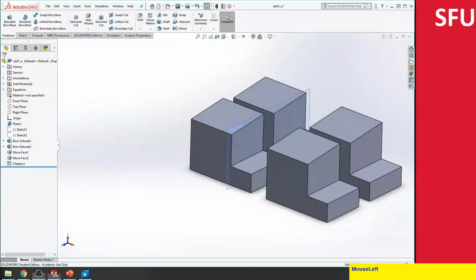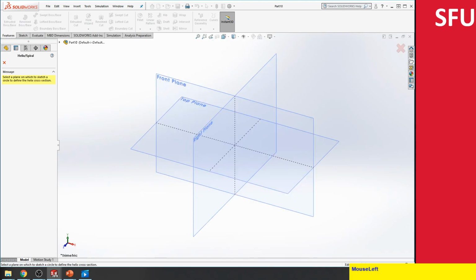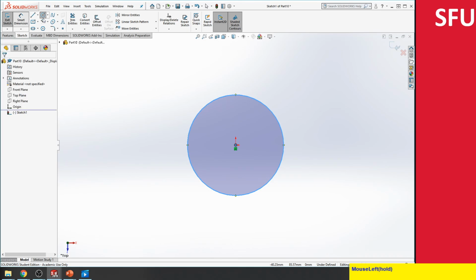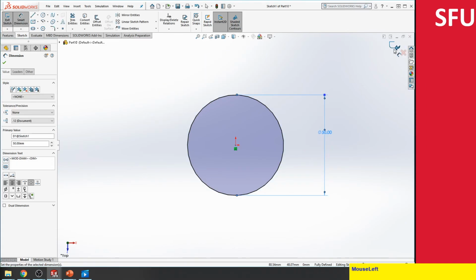So let's see. So here is my SolidWorks. So let's do a new drawing. So I'm going to go curve, helix. So it says essentially you need to create a plane to which select, so you're going to select a circle. So maybe let's create this on the top plane. So we do this. We can give it a smart diameter. And then we say OK.